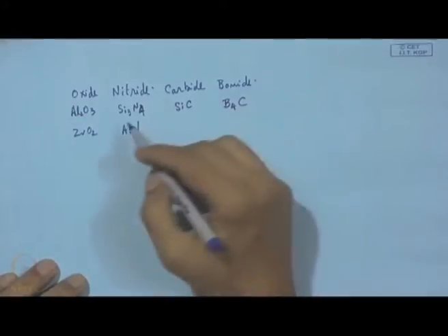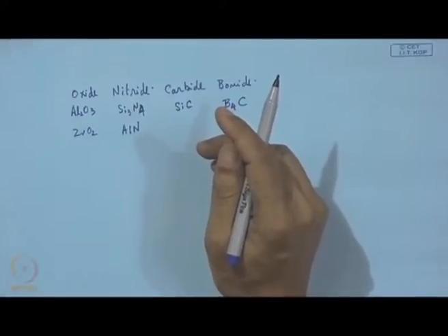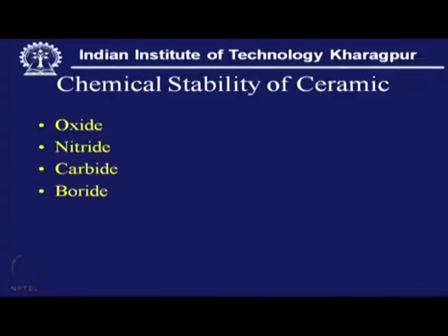ceramic. Now, these ceramics have a typical characteristic that they have a very high stability, meaning chemical stability, and because of this they show passivity towards conventional metal and they are inert towards this metal, and as such the surface of the ceramics cannot be wetted ordinarily by the commonly used metals.